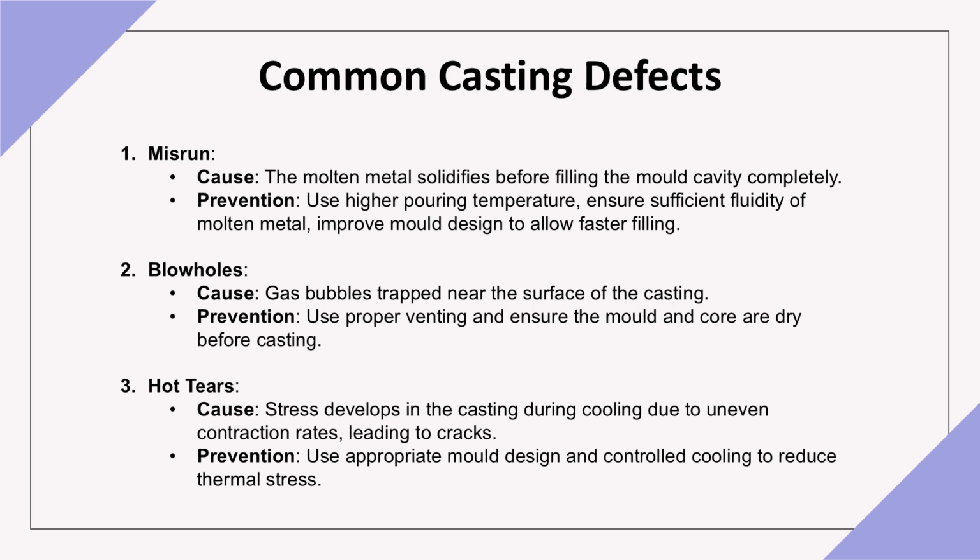Hot tears, caused by stress developing during cooling due to uneven contraction rates, resulting in cracks. Prevention includes using appropriate mold designs and controlling cooling rates to reduce thermal stress.